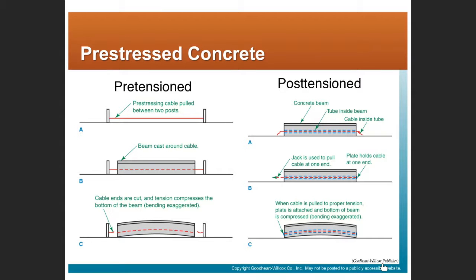So in pre-tensioning, we lay that cable out in tension because it's steel. I'm on figure 11-18 in the textbook on the bottom, and 11-19 on page 197. I put a cable in place. I put it in tension. I cast a beam around that, and then in pre-tensioned concrete, I cut that cable, and now I place the bottom of that concrete in tension.